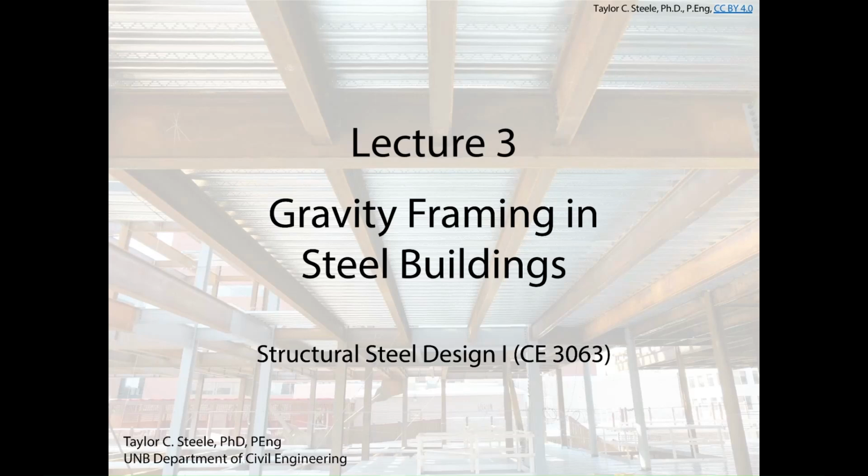And then we're going to talk about how we trace the loads from a floor, for example. If we had a uniform floor load acting on one of these floors, how do we turn those uniform loads into distributed loads on joists and point loads on girders and axial forces in columns?